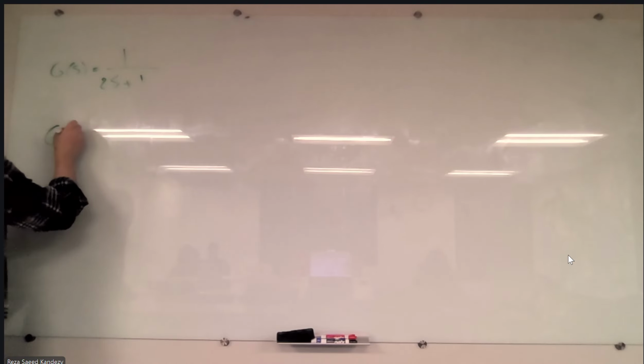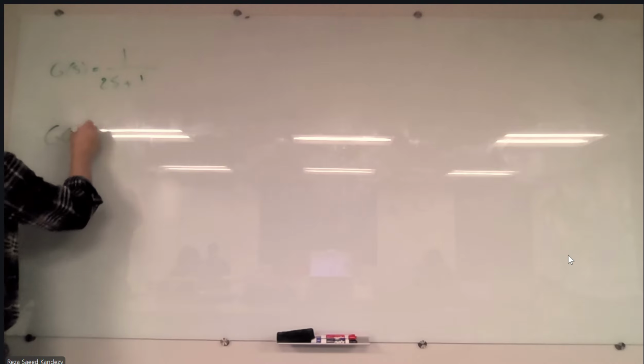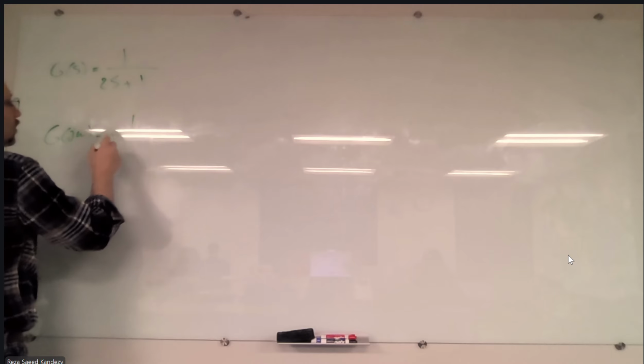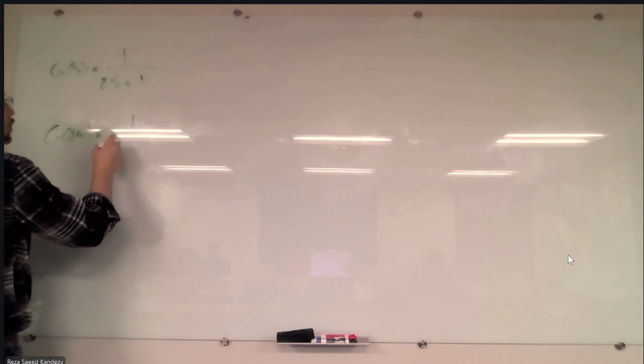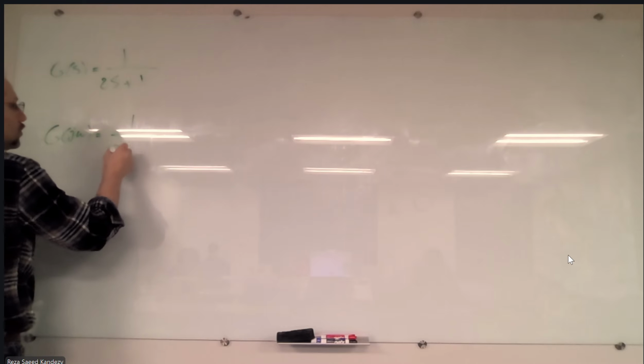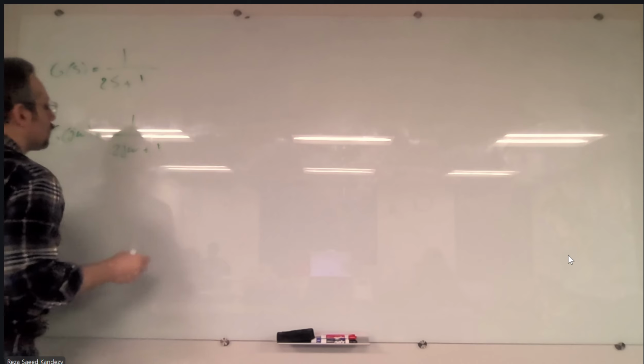what we discussed about how to draw the Bode plot was, the first step, because Bode plot is a frequency response, we need to change the s to j omega. So we are gonna move it to a simple frequency without any real value for the s. So basically the first step is to write the transfer function when s is equal to j omega. So it's going to be 1 over 2j omega plus 1.